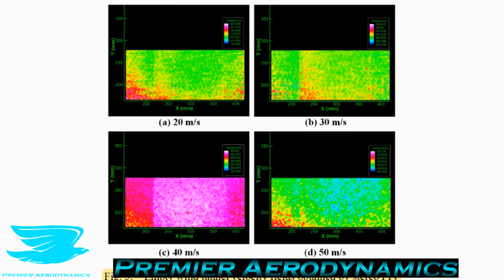Yeah, so the rest of the wind tunnel is actually quite nice. The test section, the cross section is well validated. One thing that should be noted is the higher the velocity of the free stream, the more inaccurate PIV becomes. That's because, again, the laser sheet is very thin. The particles are only going to stay in the laser sheet for so long.